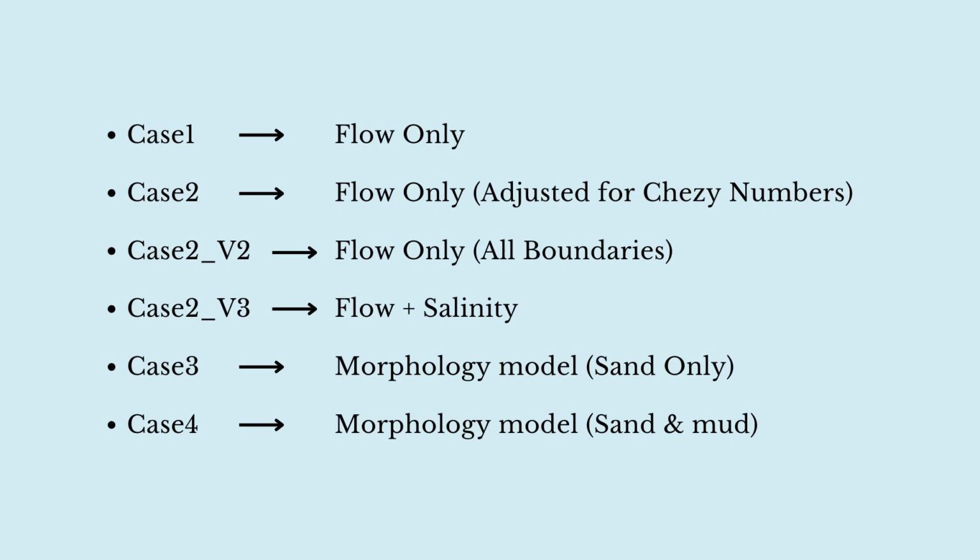So to wrap up, again, we ran two cases. In case one, we just had a south boundary. Case two, also just a south boundary, a tide boundary. We used Delft3D Dashboard to set up those models. And using Delft3D Dashboard, we extracted tidal harmonics from a global tidal model and forced that to our open boundary. The difference between case one and case two was that in case two, we used a vegetation map file to have a space-varying bottom friction. And we saw that the results changed. And in the last case, case two version 2, we saw the effect of river on water level variations.